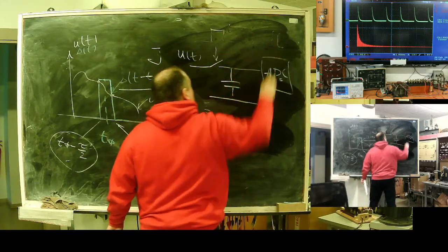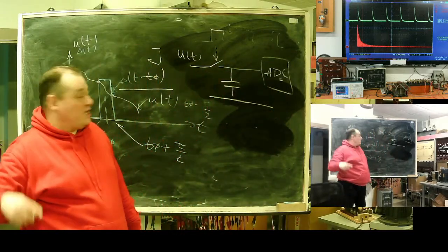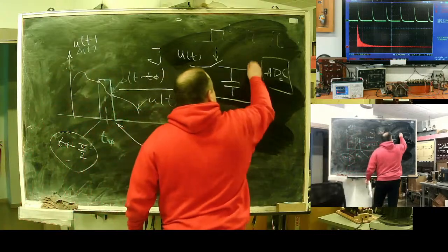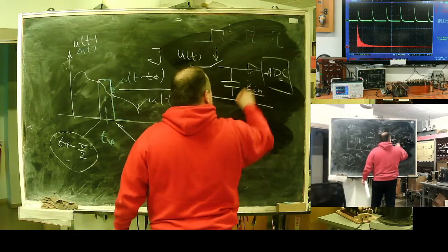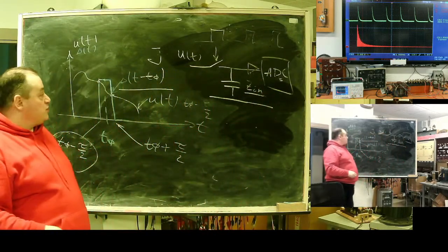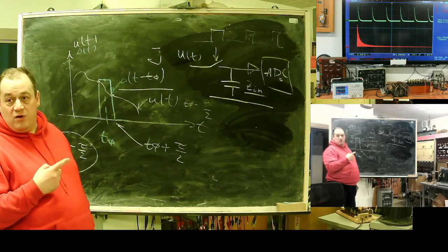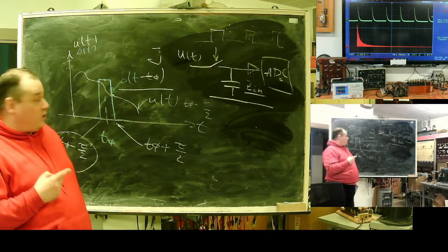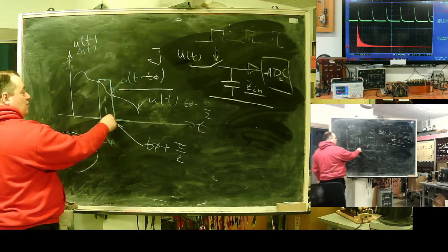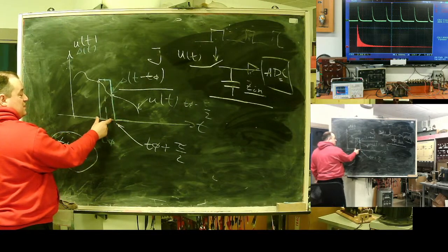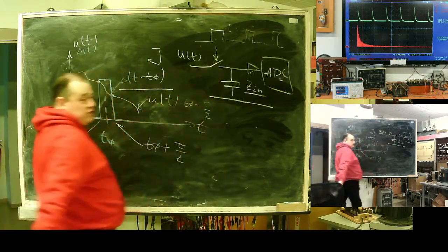Do sample, do sample, do sample. At a sampling pulse, the capacitor charges, then disconnects. Here we need an amplifier with very high input impedance, so it will hold the value until the analog to digital converter finishes its work. This is the way we will always have this uncertainty time limit with the switch property.